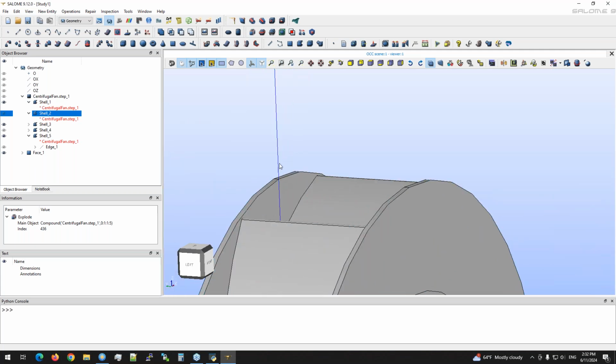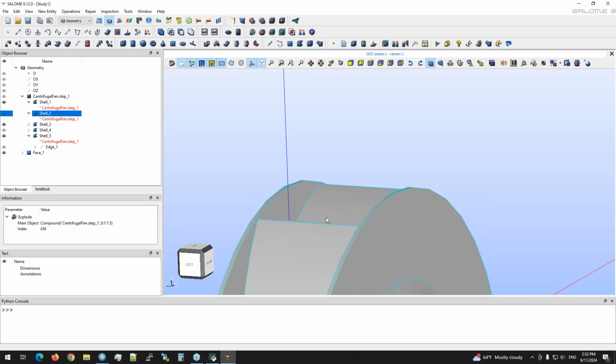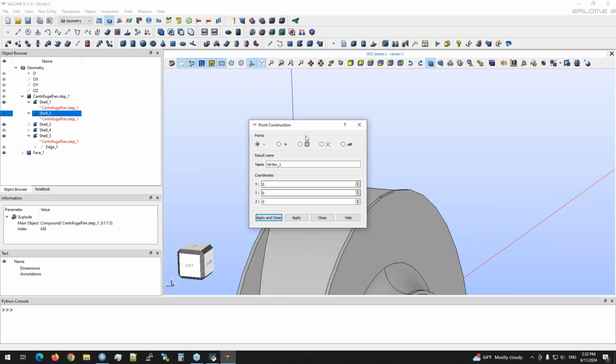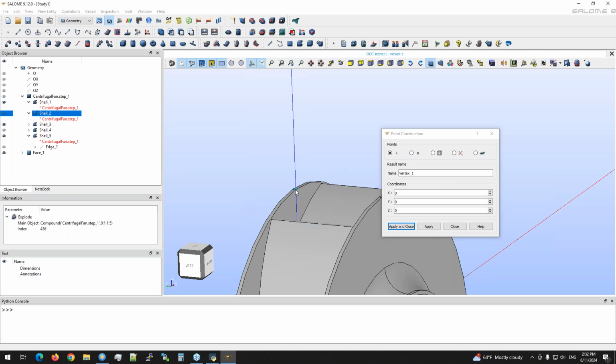So to create some kind of edge here and a rotating object, to create some kind of interface at the outlet of the impeller itself. So what can I do here? I can create some kind of leading points at the outlet from the impeller. So for example, I set the new coordinates. So I will do some kind of extension to have space for the meshing at the edges.